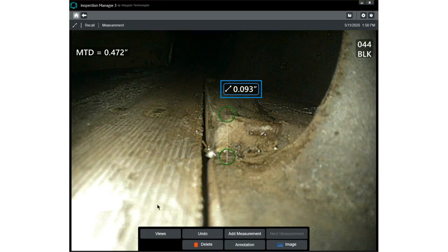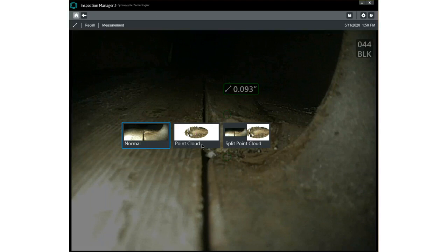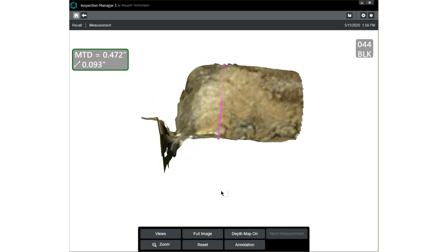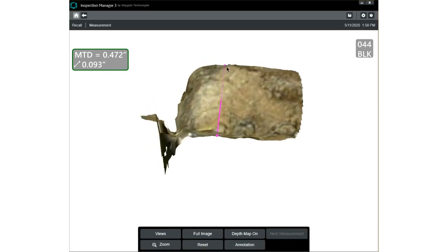With Real3D's point cloud, the idea now is never make a measurement call until you've looked at the measurement data. And what you'll notice is this cursor here on the near side stator floor is establishing a line to the next point that is not congruent to or perpendicular to the face of that stator. It's measuring off at an angle.